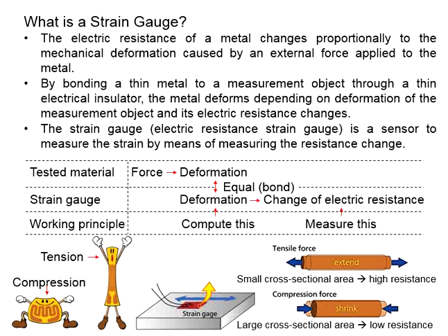To make it simple, if the strain gauge is subjected to tension, the electric foil or wire will elongate. Due to the Poisson ratio, the wire elongates while at the same time the cross-sectional area reduces. Now, having a smaller cross-sectional area, you will have higher electric resistance.